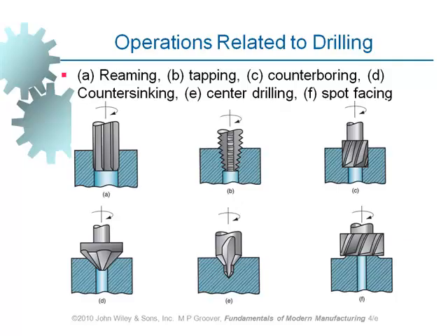in making dies. And that one is center drilling. Center drilling is used often when we want to make a really big hole, so we want to put the drill bit in the right place. First we make a center hole, then we change the tool, then we put a large diameter drill bit, and we place it at the same position, which is very accurate.